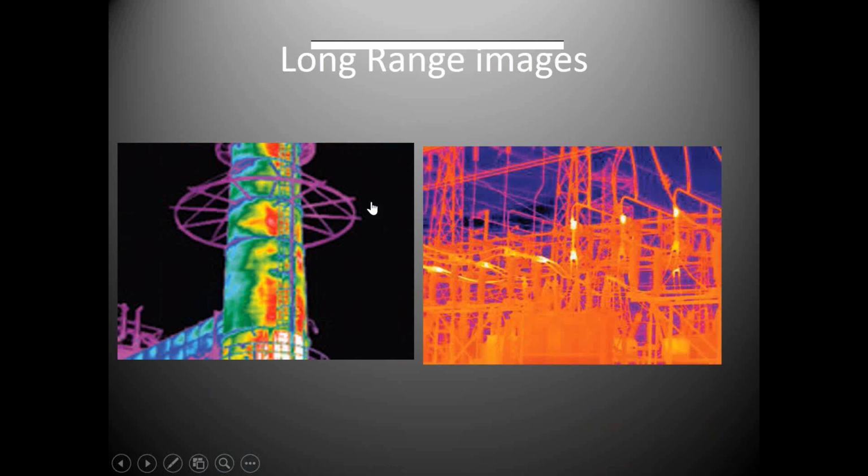Insulation on it. This was a methanol column in Texas. Now, what do you think the issues are here? The metal jacket on this insulation or this tower looks fine, but you can see the insulation underneath is probably bad. We got a lot of heat spots on there.